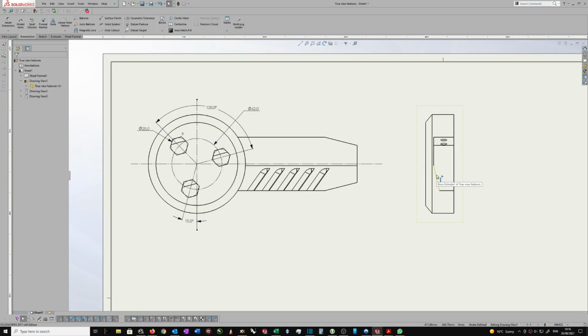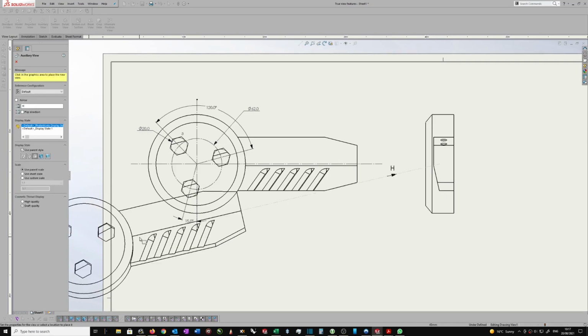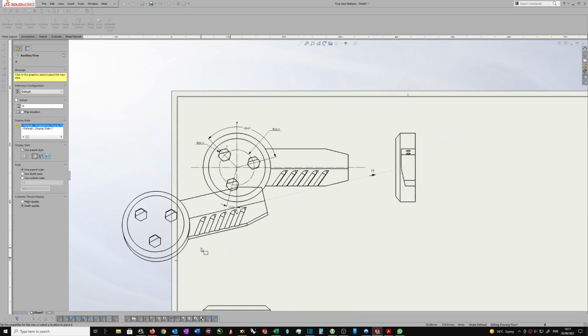In other words, a view which is perpendicular to this face. Okay, so go up to view layout. It is under auxiliary view. Select a line which you are viewing perpendicular to the plane. In other words, right now, or not perpendicular, end onto the plane. So right now I'm sort of not perpendicular to this plane, but in this view I can see the plane in its kind of representational form. So select that plane, and you'll get this view.